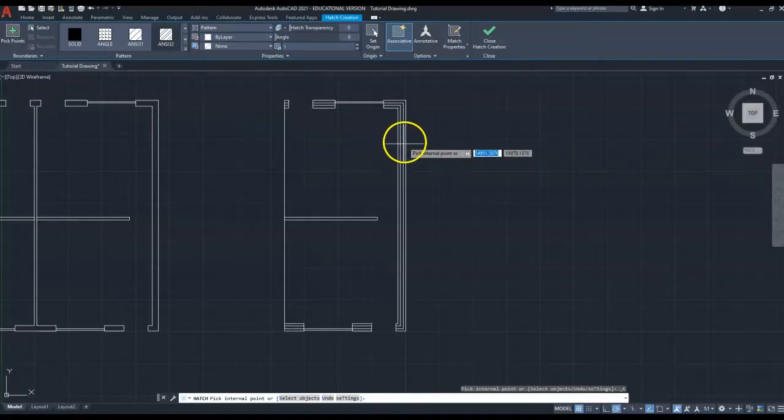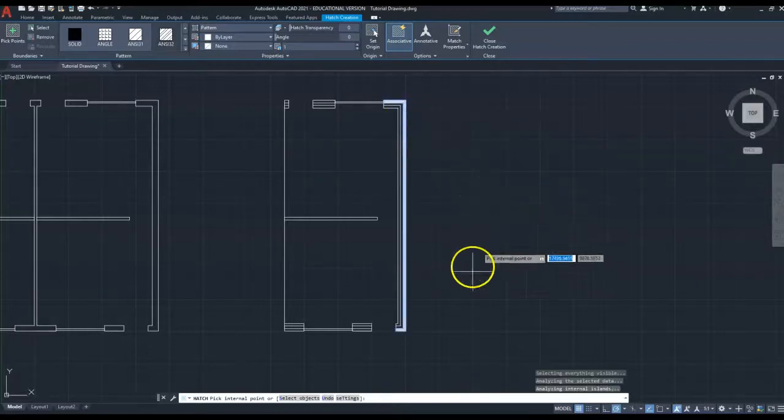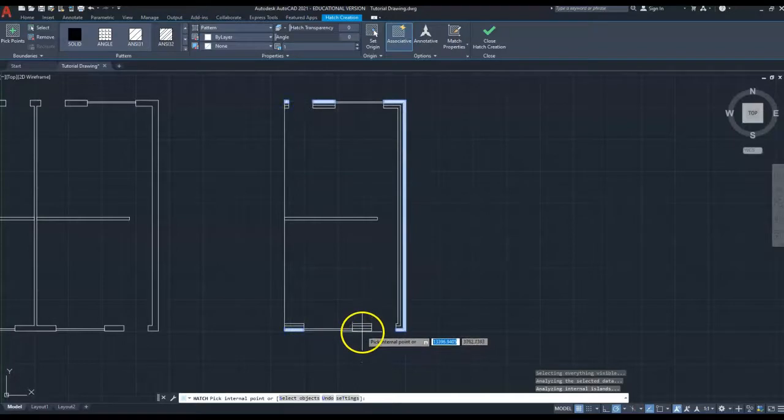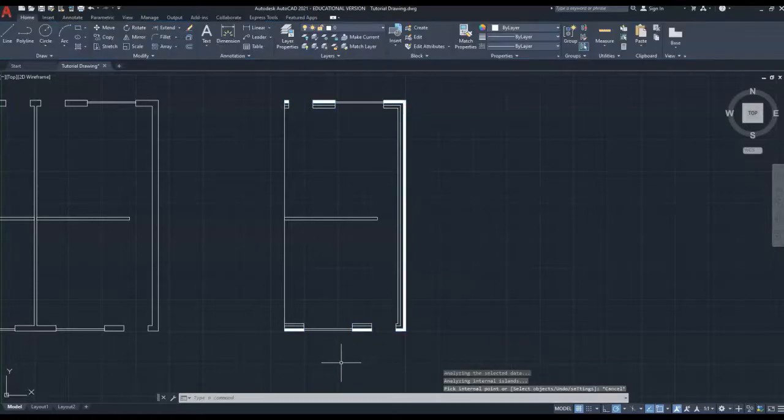So all I need to do is hold the crosshair in the inside there and click, and that just drops the hatching straight in. Okay, and I'd do the same there, there. And I'm just using the left click each time for this. So now I've put them in. So I'm happy with that, but let me click escape so I can lose the command function.